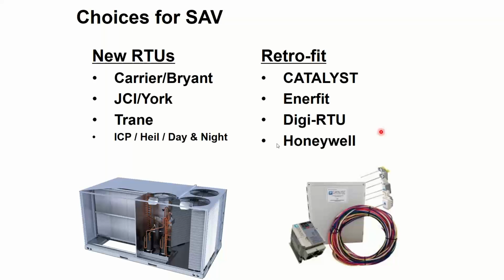Yes, you could do that. You could add this to a rooftop or air handler serving multiple zones. The only thing I would caution you on is if the zones have dampers, so it's a VAV system, then you should switch from constant volume to full-on variable air volume. Staged air volume is kind of a hybrid between variable air volume and constant volume. So if you have zone dampers, VAV dampers specifically, I would go directly to a VAV control. And it's even easier than staged air volume. You buy the same VFD you would buy for staged air volume, and you wire a pressure sensor to it instead of wiring relays to it. It's very easy to do. I've been retrofitting stuff like that for 30-some years.